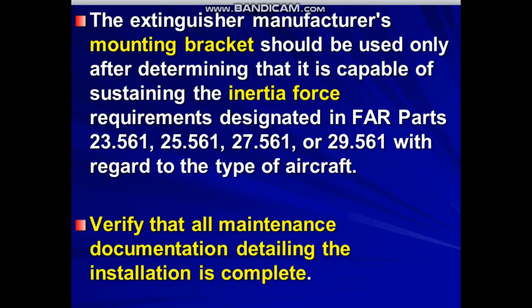The extinguisher manufacturer's mounting bracket should be used only after determining that it is capable of sustaining the inertia force requirements designated in the FAR parts 23.561, 25.561, 27.561, or 29.561, with regard to the type of aircraft.